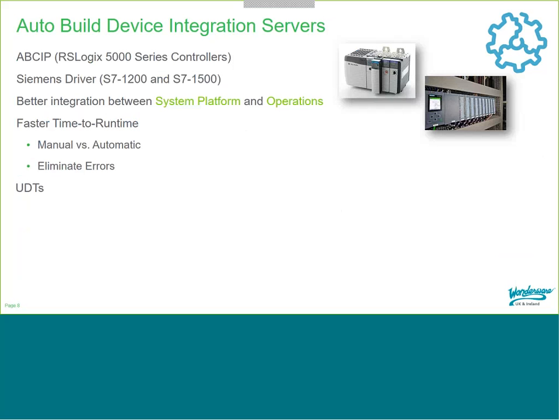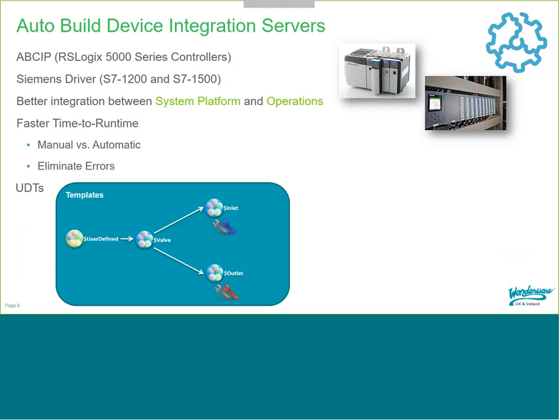They've also got, now very recently, a new Siemens driver that communicates to S7-1200 and 1500 PLCs. And what this does is allow you to essentially suck the values out of your PLC and import them into the System Platform environment. So it'll do all that for you. You can import thousands of references from your PLC straight into System Platform and already have the correct structure built up, providing you're using things like UDTs in those PLCs. UDTs allow us to define a similar structure to what we'd normally expect inside System Platform. System Platform's all template-based anyway, so it matches up nicely.